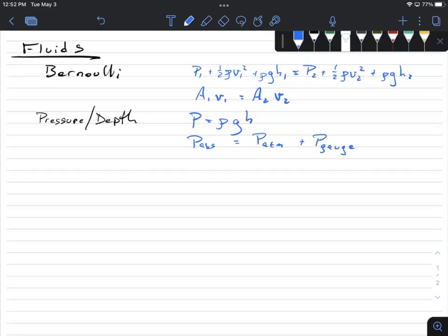So the pressure depth relationship, that's the gauge pressure equation. Because all this does is keep track of how much extra pressure you feel as you dive down. It doesn't tell you the fact that you're already in the atmosphere. And so because of this, when you read a question that has to deal with this stuff, you have to be careful to see what it is asking for. Am I asking you for the total pressure or the absolute pressure? Then you better include atmospheric pressure.